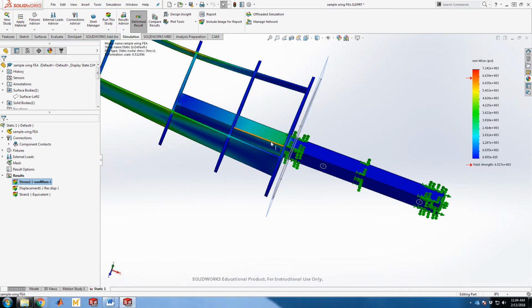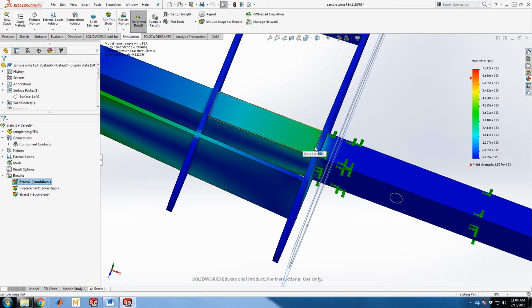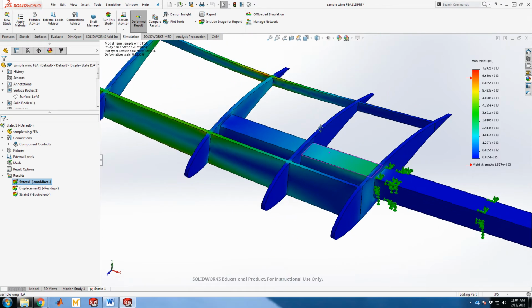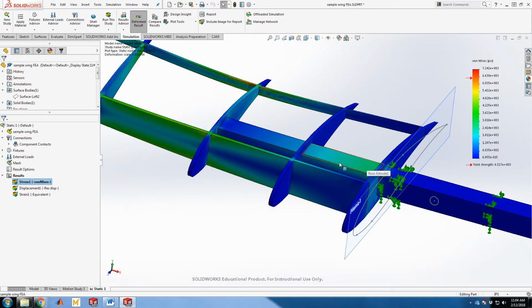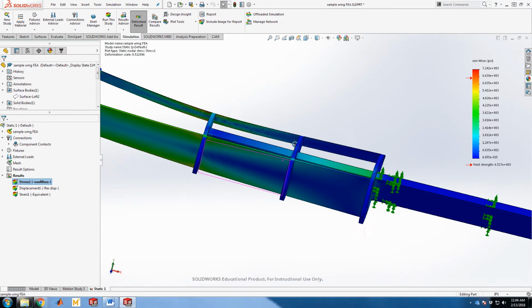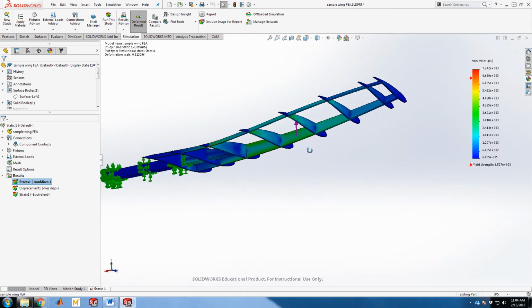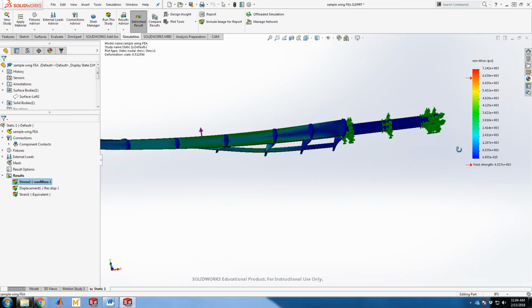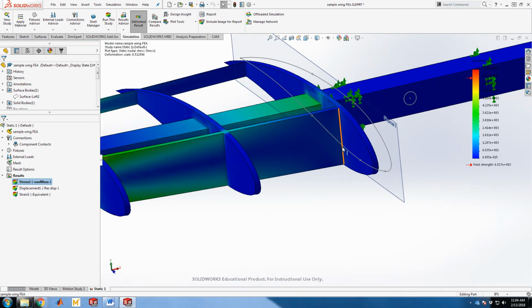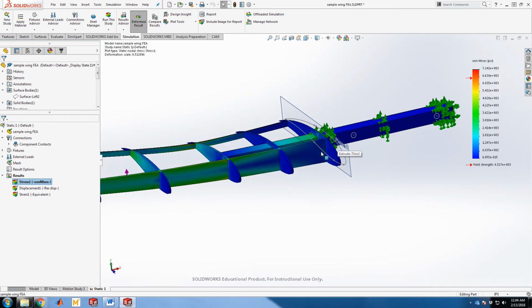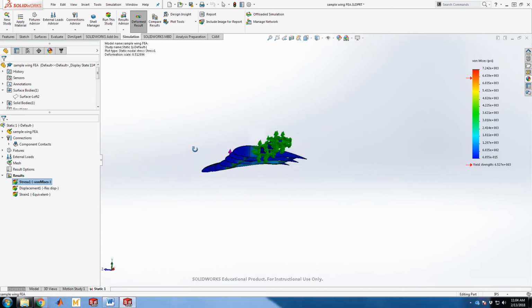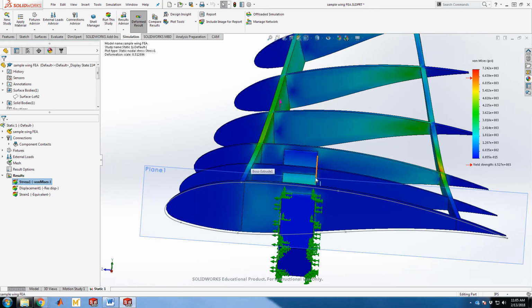You can see that the load is actually staying mostly in this central spar through the first gap of the ribs, and then you formed enough of a couple with these other rib connections to the fore and aft spar that now you've seemingly effectively transferred that load out to the spars. But it's interesting that the main tallest spar is virtually unloaded here at the root. So now the stresses are down in like the 7,000 range, so that's more reasonable. Even maybe a plastic wing could withstand this.